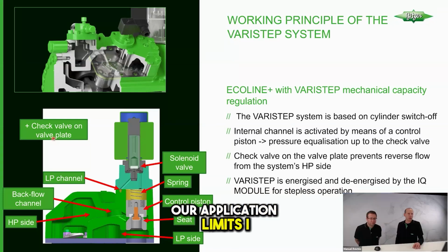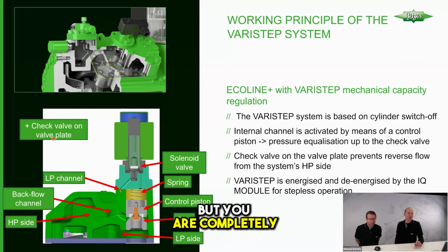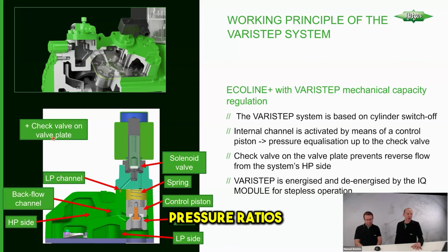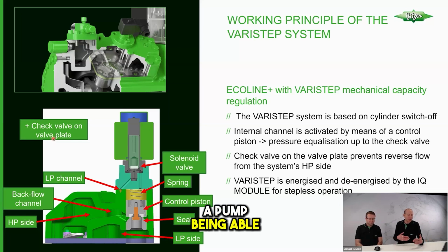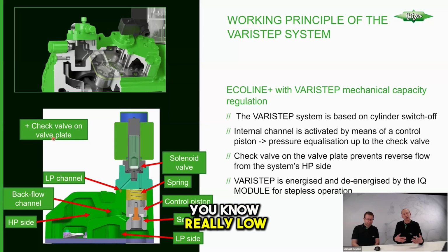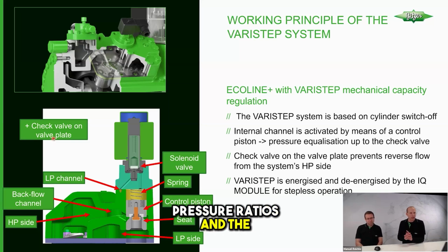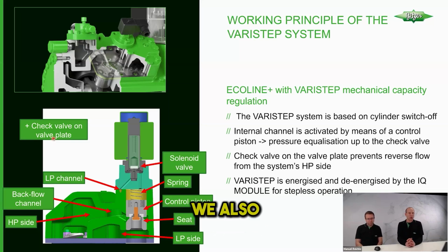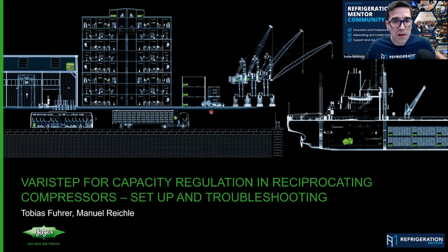Our application limits, within what we publish, are tested and verified, but you are completely right. At lower pressure ratios, at some point, the valve plates no longer function properly. A compressor is not a pump able to do really, really low pressure ratios. That is why we also publish where it can be used and where it should not be used.